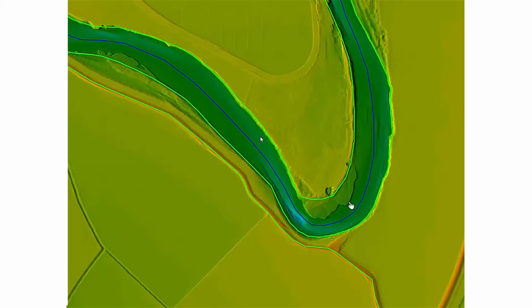Now in this case, because we have a river channel running through our study area, we can use something called the directional mesh. Directional mesh is essentially a rectangular mesh that follows a center line, so the 2D cells are drawn perpendicular to that center line. The advantage to this is that your 2D mesh can follow the natural flow of that river channel, if it's known, and it also keeps your model smaller. By using a rectangular mesh, there's actually only 4 conduits drawn per 2D node, as opposed to 6 with a hexagonal mesh.